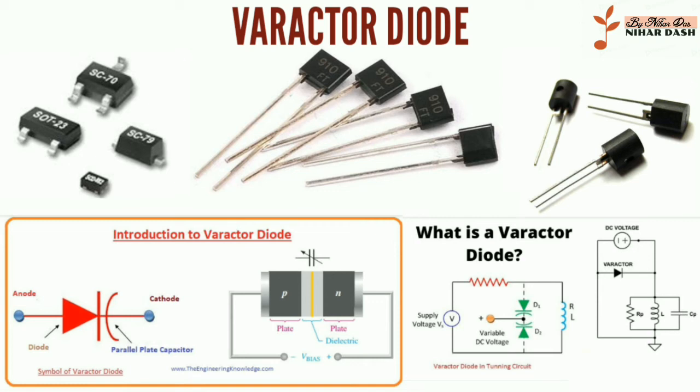Reverse bias PN junction diode: the varactor diode operates only in reverse bias. Because of reverse bias, the current does not flow. If the diode is connected in forward biasing, the current starts flowing through the diode, and its depletion region decreases. The depletion region does not allow the ions to move from one place to another. The varactor diode is used for storing the charge, not for flowing the charge. In the forward bias, the total charge stored in the diode becomes zero, which is undesirable. Thus, the varactor diode always operates in the reverse bias.